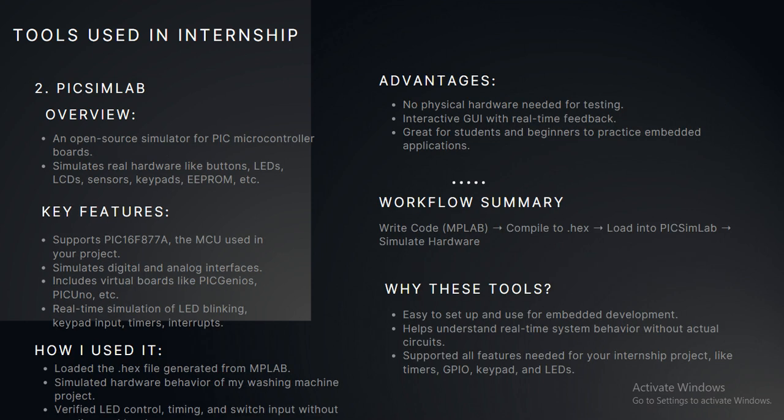And also I used PICSimLab. PICSimLab is an open source simulator that replicates PIC microcontroller hardware. So we can use it in our software like that. It allowed me to test my washing machine logic using virtual LEDs, digital keypads, and LCDs without needing real hardware. I loaded the compiled hex file from MPLAB into PICSimLab for real-time simulation.